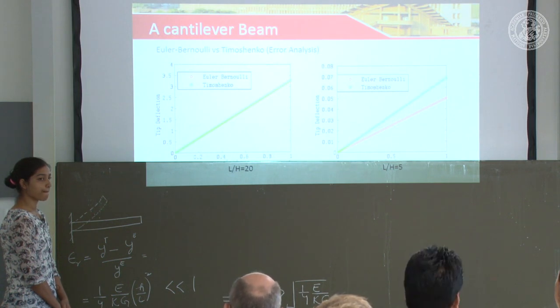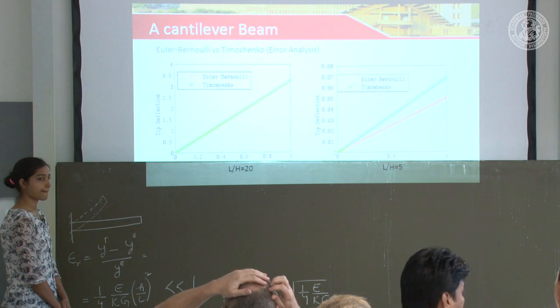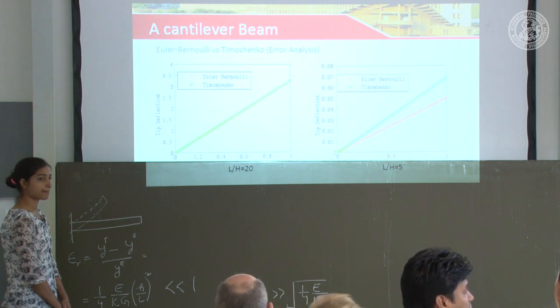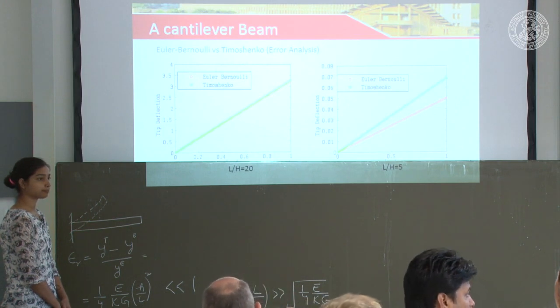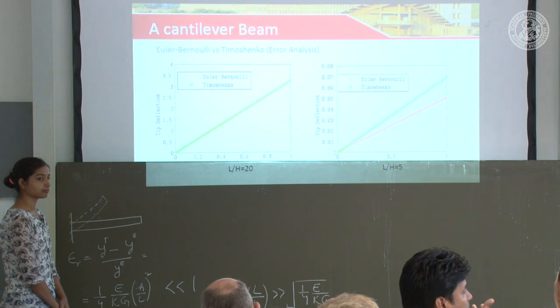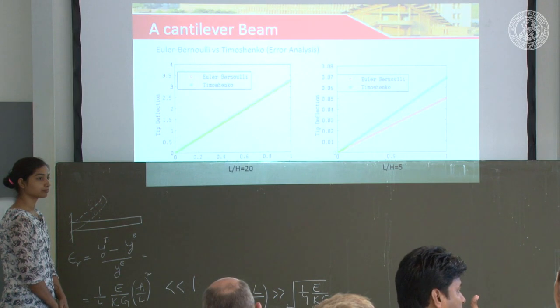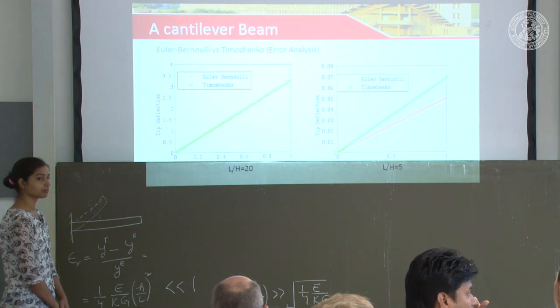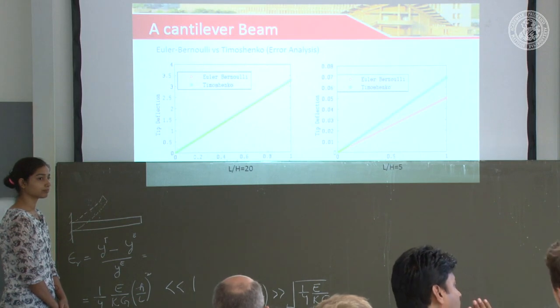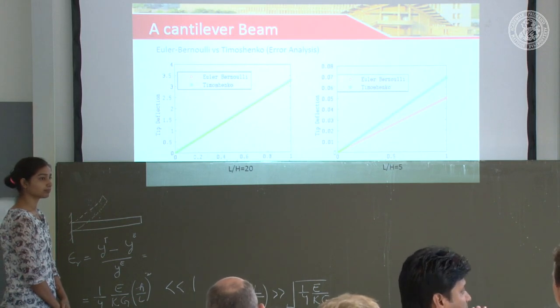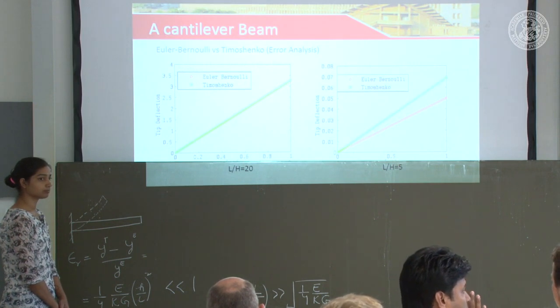What will come here would be the ratio of area of the cross section and the moment of area about the axis in which it is deflecting. So the other moment of area will not come in the picture. Only if you are deflecting in, let's say, the other plane, then that moment of area will come in the picture with the area of the cross section.